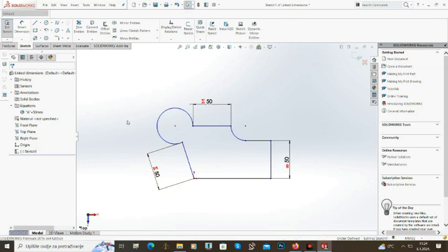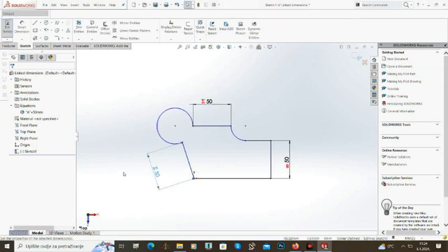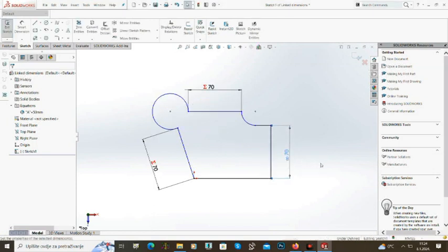And now, for example, we want to change all of those dimensions to 70. We can't go here and change this to 70. It's not possible, right? Let's click OK. You see, it's not possible. Neither this one. If we want to change those dimensions, we can only go here to the main one, which is linked to the variable A. So go here, double click, and just change this to 70. And now simultaneously, those two also change to 70.